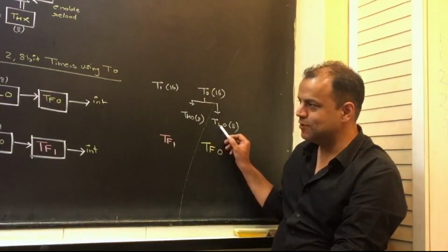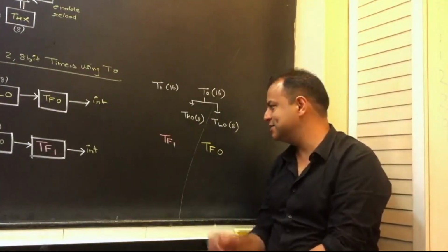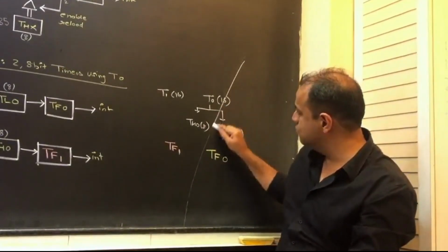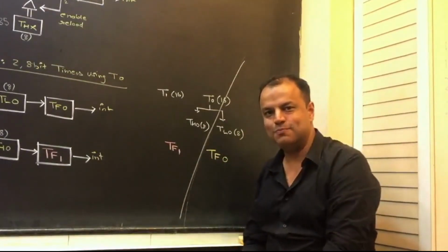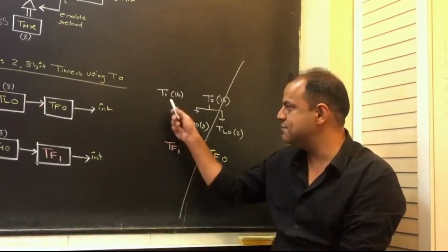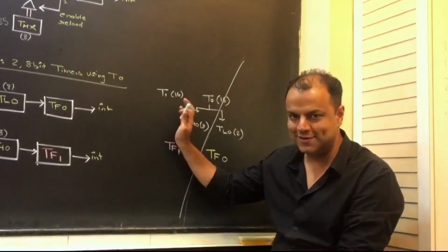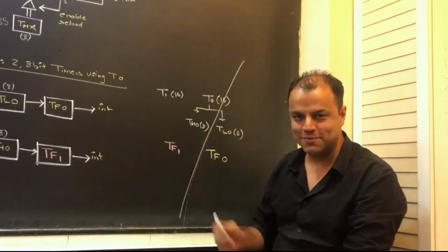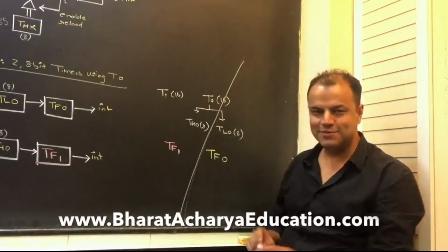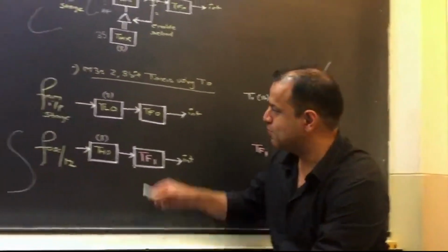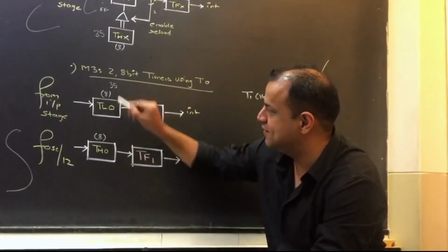First, timer 0 lower byte. Timer 0 lower byte says enough. Earlier we were 1 timer. Now let's go our own ways. Let's part ways. I want to be independent, you be independent. Timer 1, there is no problem. It is still 1. Timer 0, lower byte and higher byte want to go their own separate ways. So we start with timer 0 lower byte. Timer 0 lower byte wants to be an 8-bit timer, no problem. We give it a count, something like 35.